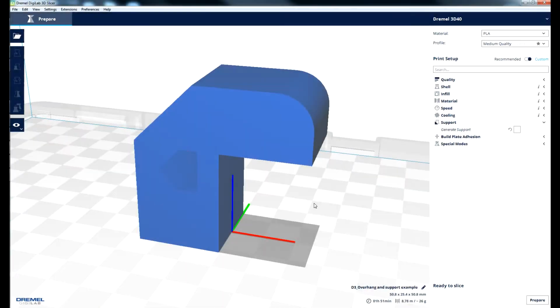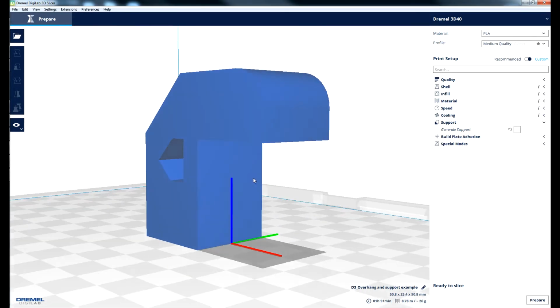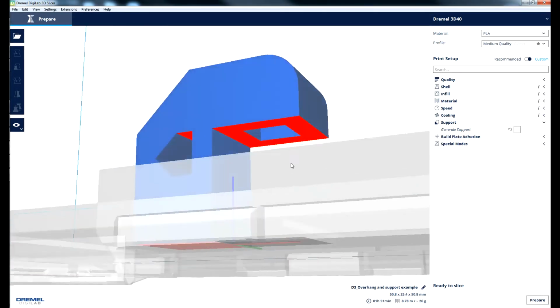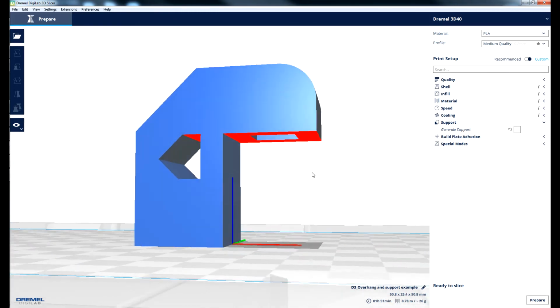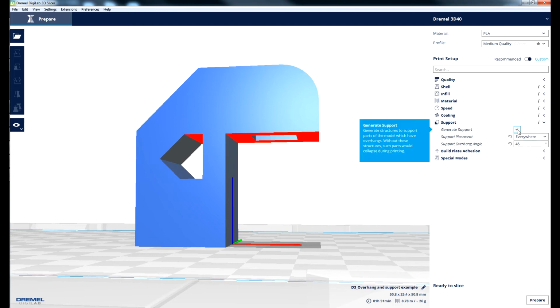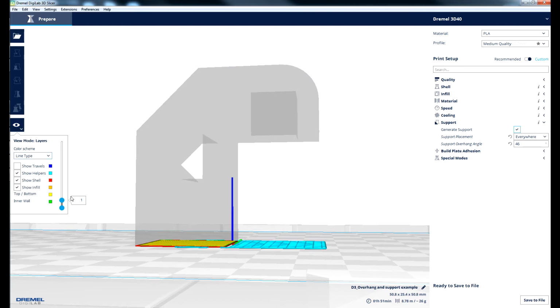There will come a time when you need to have the slicer generate support structure to build your part. This is very common. Fortunately, this feature is automatic as long as you have the feature called supports turned on. Overhangs that exceed 45 degrees or elevated features above the build plate need support. Overhanging features are usually identified by a red colored face on the surface of your part.